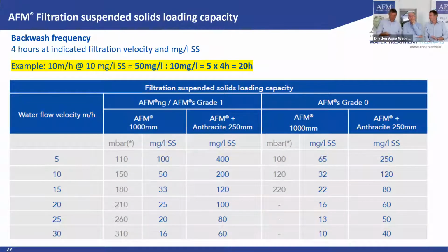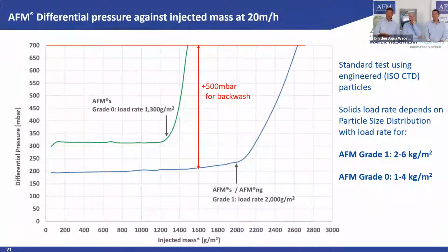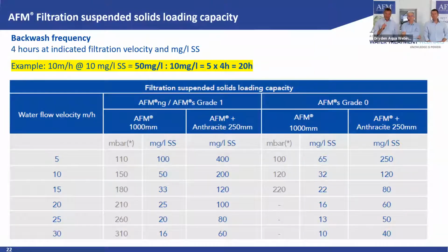Every 4 hours. And that's really the worst case scenario, right? And this comes from this data here. Now, again, in reality, because you're at 10, the reality will be bigger. How much bigger? We do not know. It also, as you mentioned, depends a little bit on the particle size distribution of the suspended solids.